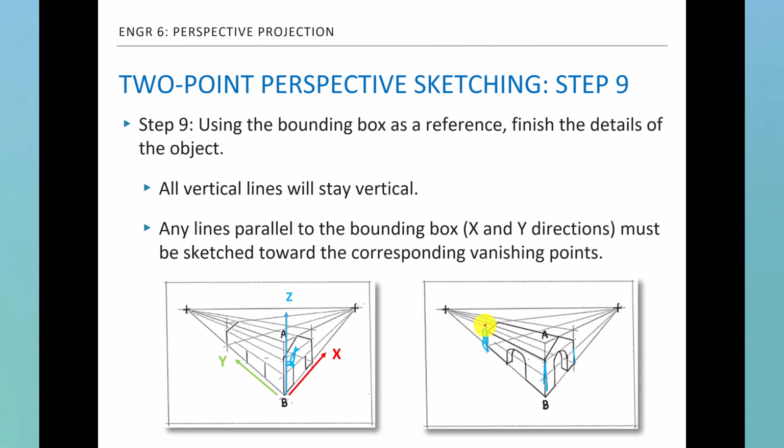You have to measure the object length directly from the drawing, but if that involves a lot of calculations, which is very difficult, that's not a good way of communicating for manufacturing. That's why we use orthographic projection, not perspective projection, although the perspective drawing looks more natural to your eyes, because that's how we actually see.